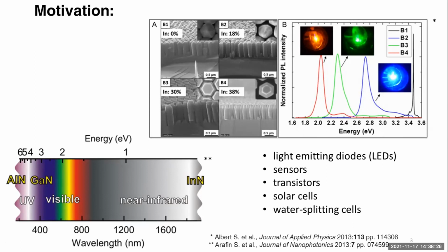growth of III-N nanowires on silicon substrates is often accompanied by a high density of nanowires up to their full coalescence. As a consequence, this imposes restrictions on the creation of radial core-shell heterostructures based on III-N materials.